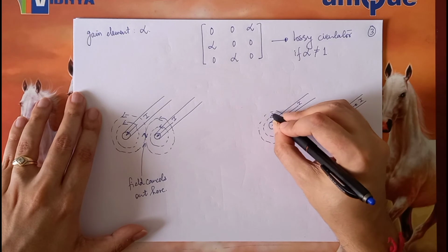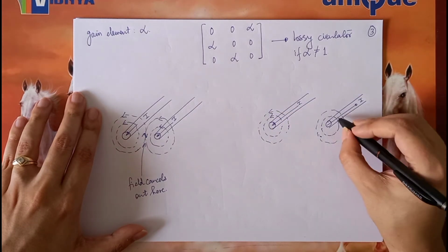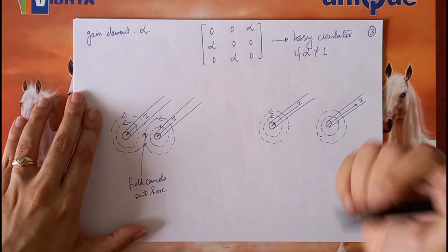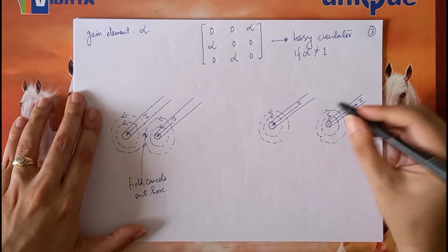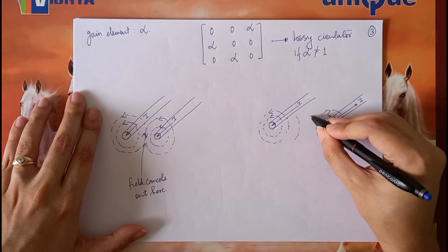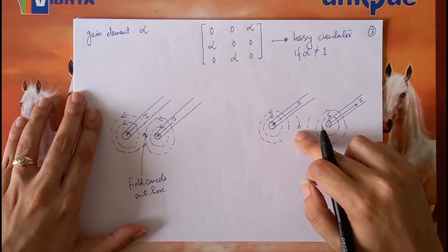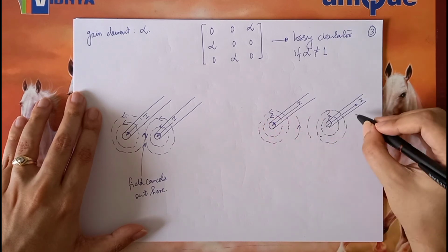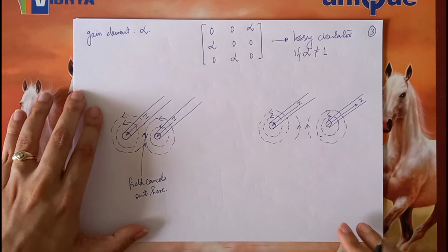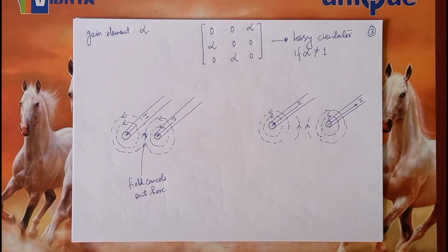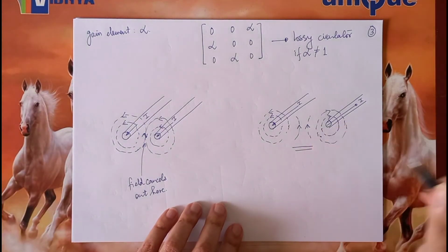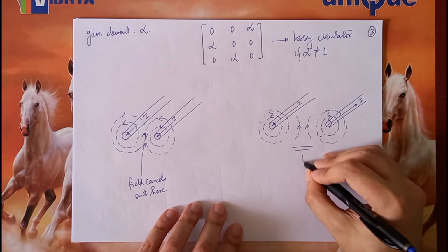So here again the direction would be this way, but here the direction would now be this way. So in the middle, if I have the field lines from either side, for the left conductor the field direction would be this way, and on the right hand side the field direction would be like this. So therefore fields would now add up because they are in the same direction.